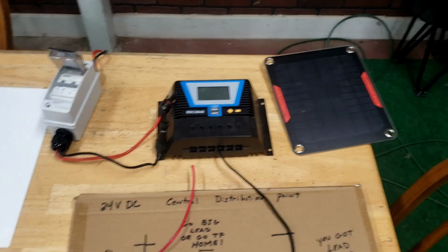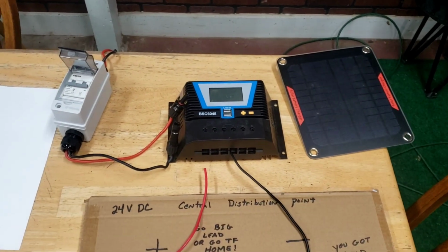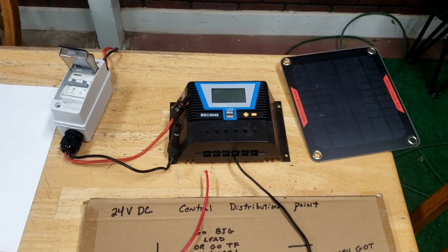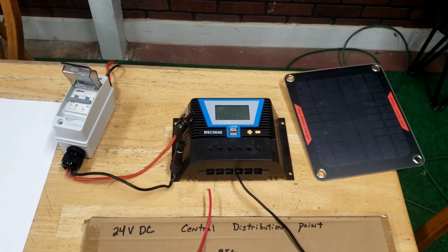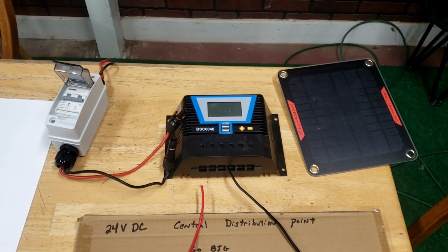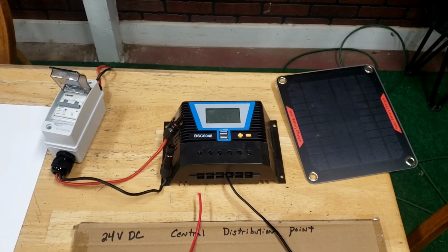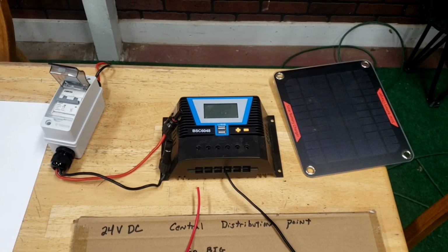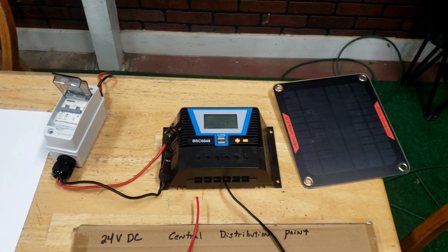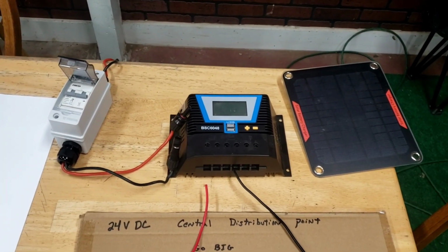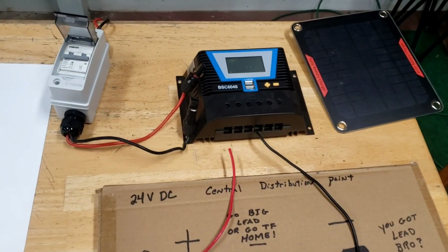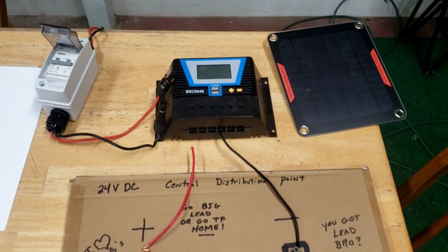So now our solar's running full blast. We'll say we have 2,000 watts of solar out on the roof. Again, we're back to the watts. But this time, rather than it being work, those watts are coming in to do work and charge the battery, or those amps. And that would be about 85 amps.